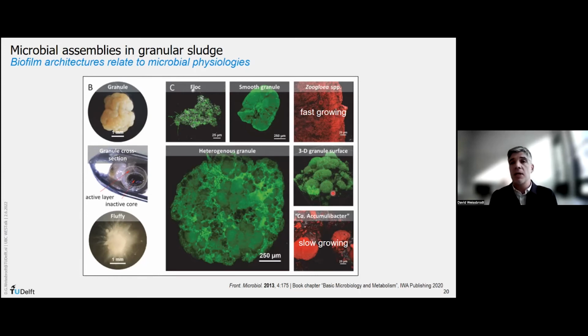So granules are made of microorganisms, and there are also some organisms that we don't want. They are filamentous organisms, and they will lead these granules of flocs to settle very slowly. You see these filaments here. And this is problematic for wastewater treatment plants. You don't want them because of the settling afterward that is impaired.